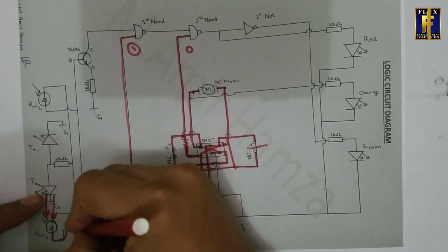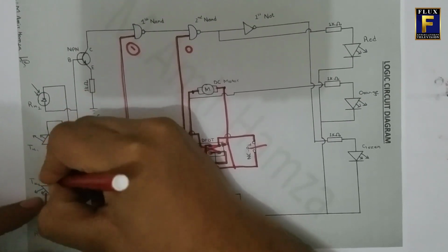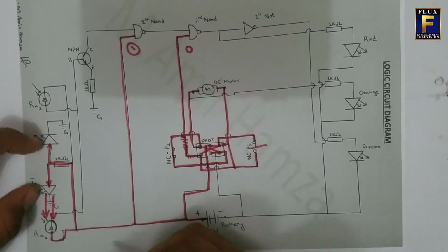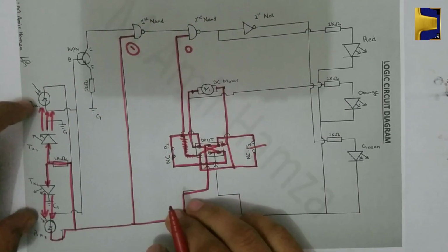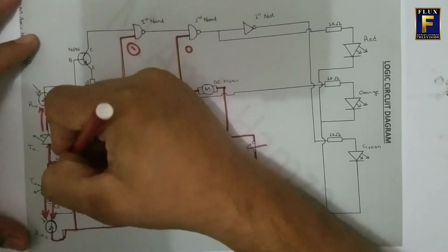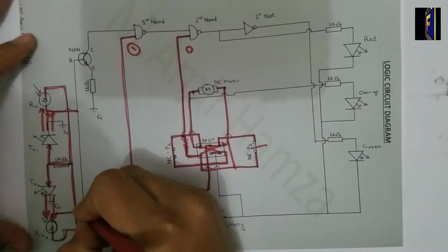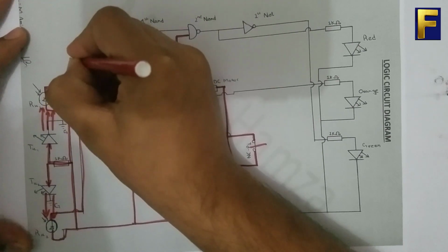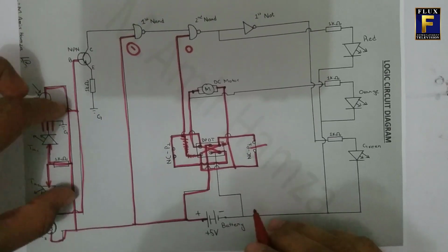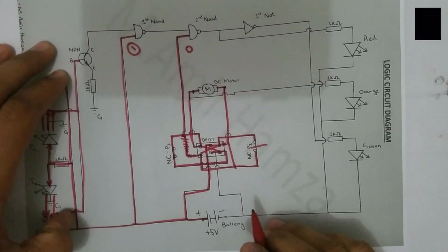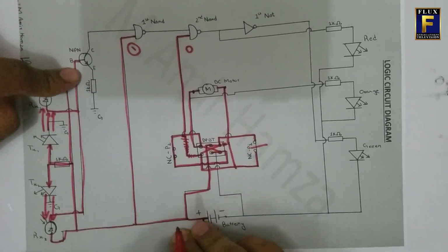So when the transmitter, the receiver, the rays, the positive which was going into the transmitter will operate the transmitter, and the transmitter throws the rays to the receiver. And what will happen is the receiver receives those waves and completes the flow of the current, and by joining both currents, it will input to the NPN transistor. Now the input coming from the receiver is not powerful enough to operate the NAND gate or any type of gate, so I'm using the NPN transistor here.